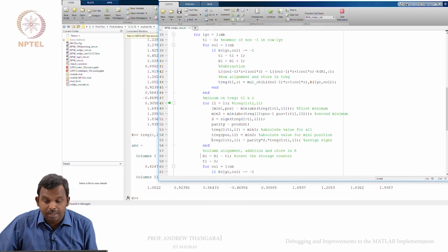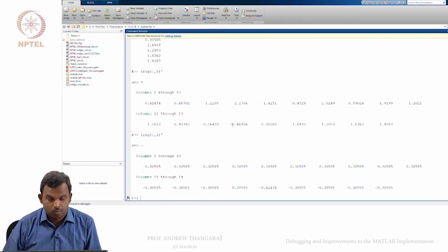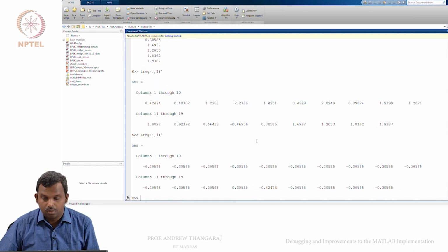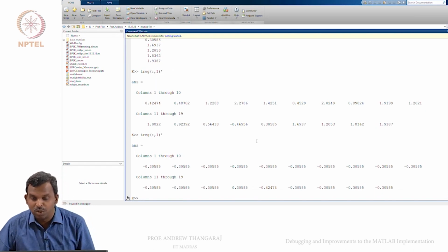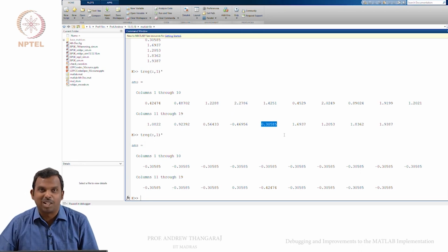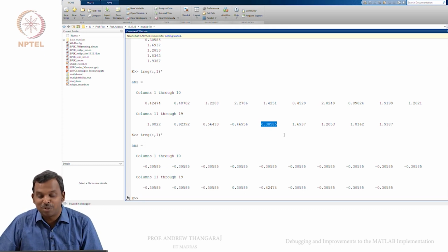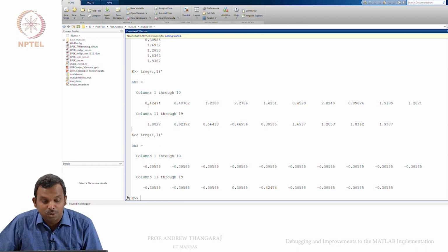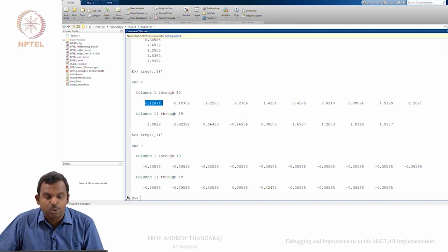So we'll run through the min sum just for this guy, and then we step and see the same thing again. Okay, all right. So I missed one value as usual, not very surprising. It looks like 0.30585 is min 1. I'm sorry. This can happen if you do it manually. These kinds of errors can happen. Of course, the program is not going to make that error. So min 1, I was totally wrong. It was not 0.42474, it was 0.30585, and min 2 was 0.42474.